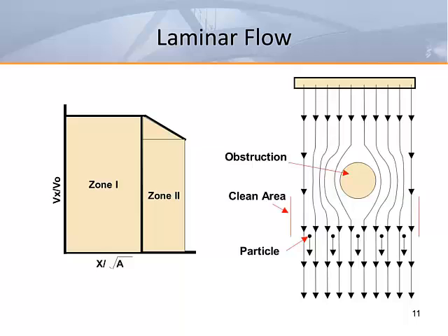Where higher velocity air jets can be deflected by objects in the airstream, these low velocity airstreams tend to flow around the objects and redevelop on the other side. ASHRAE Standard 170 requires that no more than 30% of the primary supply diffuser array area be used for non-diffuser items such as lights, gas columns, etc.